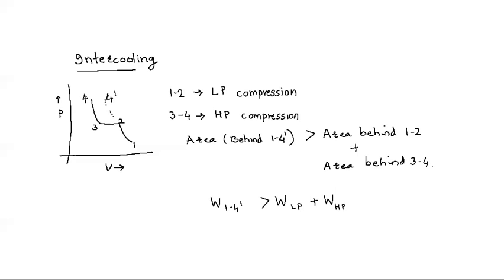Anybody who is exposed to the theory of compressors will know that intercooling, and we had talked about the reciprocating compressors, would facilitate the reduction in compression work. This is generally a theory for compressors. So this also is applicable in case of a refrigeration system. Now, how is the intercooling achieved in case of a refrigeration system, especially when you are talking about the multi-stage system?